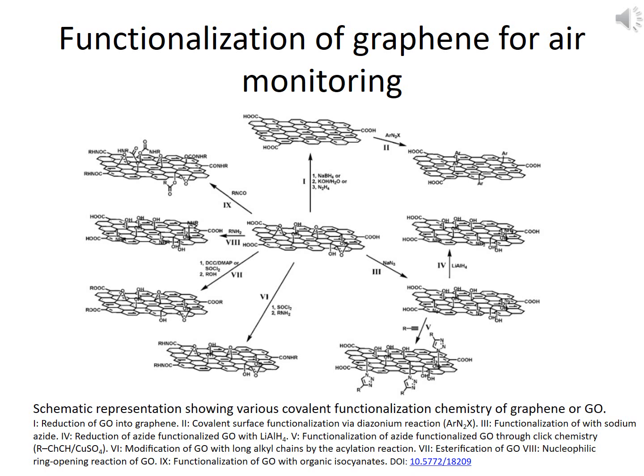For example, one doped graphene shows characteristics of the N-type semiconductors when it is exposed to a reducing gas, such as ammonia. It would get electrons from the gas molecules, leading to an increase of the electron concentration. That is, a decrease of graphene resistance occurs. Likewise, when it is exposed to an oxidation atmosphere, such as nitrogen dioxide, it will deliver electrons to the gas molecules, leading to an increase of the hole concentrations and therefore to an increase in the graphene resistance.